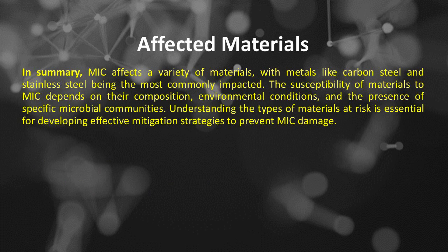In summary, MIC affects a variety of materials, with metals like carbon steel and stainless steel being the most commonly impacted. The susceptibility of materials to MIC depends on their composition, environmental conditions, and the presence of specific microbial communities. Understanding the types of materials at risk is essential for developing effective mitigation strategies to prevent MIC damage.